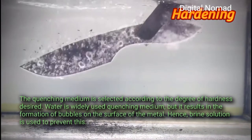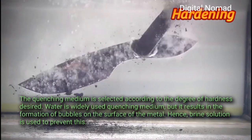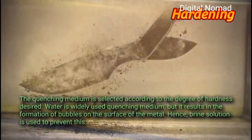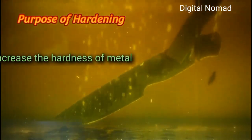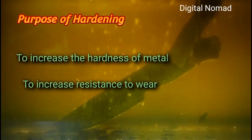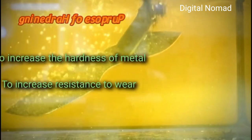Water is a widely used quenching medium, but it results in the formation of bubbles on the surface of the metal. Hence, brine solution is used to prevent this. Purpose of hardening: to increase the hardness of metal, to increase resistance to wear.